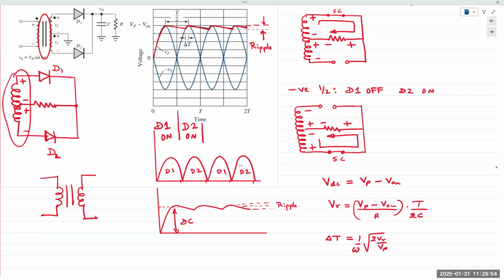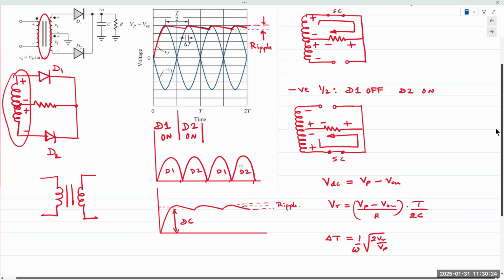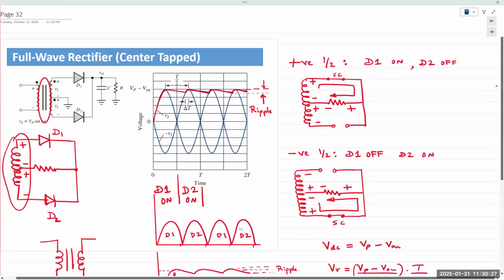And as a step down transformer, we are stepping down from our power outlet all the way down to like 20 volts or less. So it'll always be a step down transformer. So winding will never be equal. If the winding is equal, then if we apply 120 volts from our power outlet, the output of the transformer is also 120 volts. So winding coils, the turns ratio would never be equal. But the obvious disadvantage here is that you need a special kind of transformer.